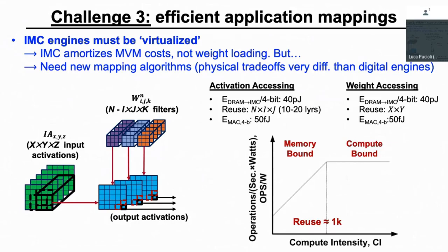One interesting insight that I'll give you, and I don't have answers here yet because, like I said, this is ongoing research. But one very interesting insight here is the fact that in-memory computing has this density advantage by exploiting these bit cells. Turns out that these virtualization overheads are often kind of communication overheads. You're loading new configuration bits or new weights. In fact, by reducing the size, increasing the density, you can do a lot to actually get gains in this virtualization overhead. But we need new algorithms. We need algorithms that take advantage of that opportunity.